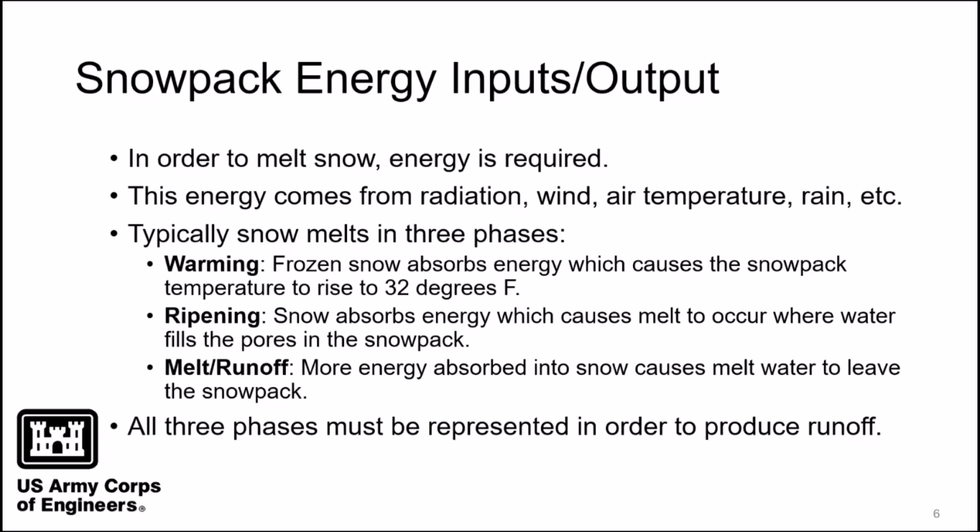It's a porous media that has ice, air, and water in it, and the amount that can be held before any kind of runoff happens typically varies between 3 and 8%, but can even go up to 15% for particularly slushy snow. And that period is called ripening.